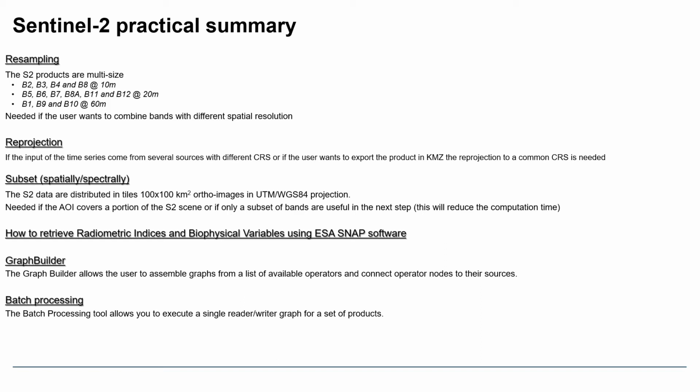I will show you how to retrieve radiometric indices and biophysical variables, and also present Graph Builder and how to build and use a graph with your processing chain. And after, using the batch processor, we will run our graph for a set of products.